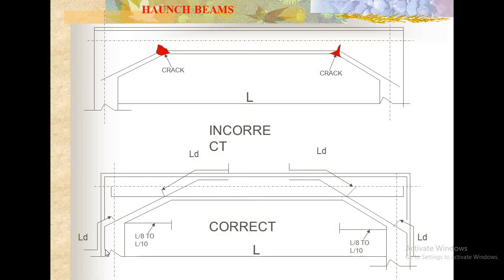So this bottom reinforcement starts from the outside of the column. It is bent like this. You see, this reinforcement is extended to the top. Likewise, here the bottom reinforcement starts from the outer face of the column, and it extends like this, and an additional horizontal bar is also provided.